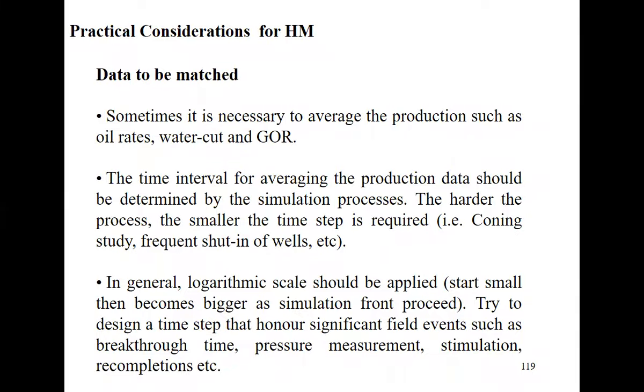So sometimes it is necessary to average the production such as oil rate, water cut, and GOR. The time interval for averaging the production data should be determined by the simulation process. The harder the process, the smaller the simulation time step required. Coning studies frequently show this in the wells.